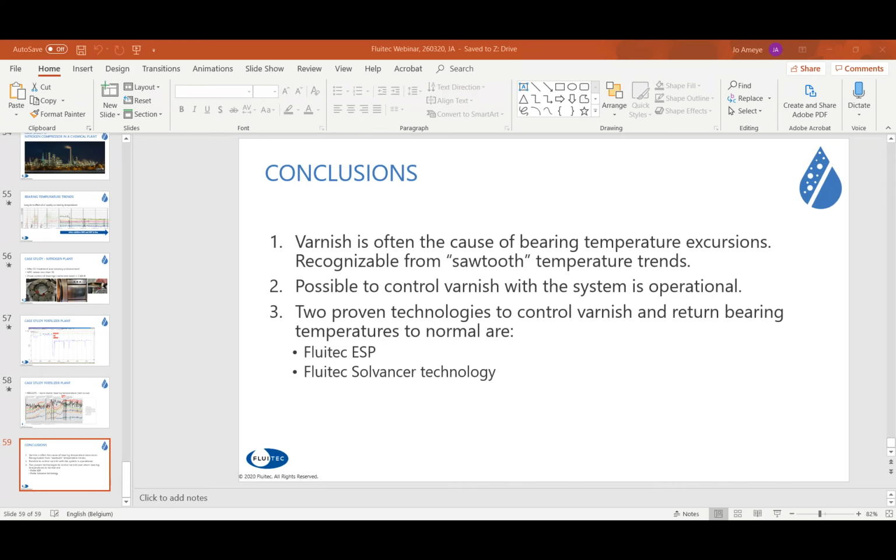And the best thing is always to run oil analysis. If you want to have certainty, run your MPC, run your RULER, run some of your air release and foaming tests. If you have varnish, all of these parameters will give you a good indication. With sludge, mostly not. MPC will not be affected by that, neither will foaming. So yes, that is the difference.